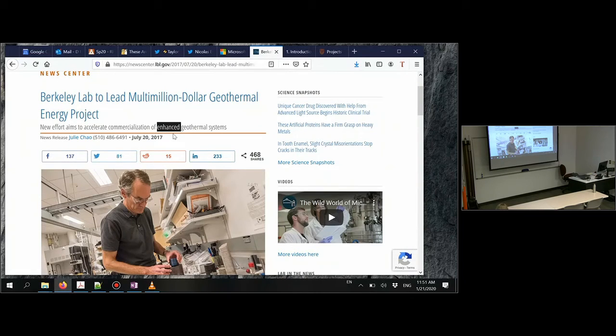Let me tell you what's the problem with current geothermal energy. Just drilling one wellbore is not enough. It's not enough surface area. Some of these rocks, which are very hot, have a very low permeability. So it's very difficult to have a very good heat transfer because you cannot really get the fluid to flow through the rock. Everything that you get is mostly from the wellbore. So if you wanted to increase the surface area, if you wanted to have more contact of that cold water with the hot rock, what could you do?